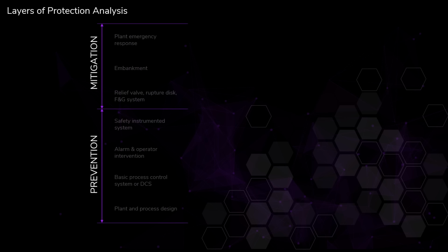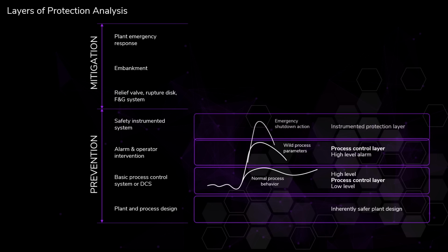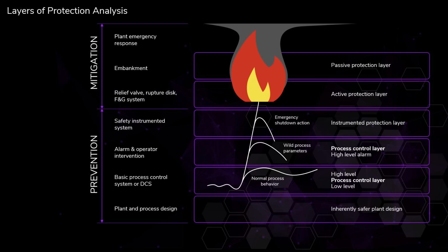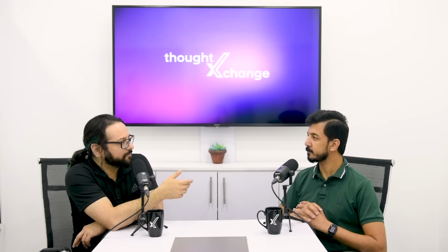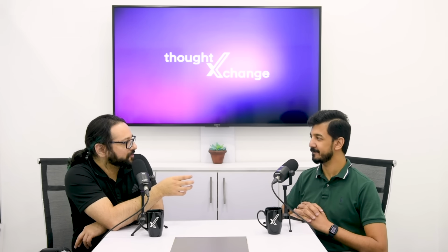That is again governed by IEC 61508. That is layer of protection analysis. So what is layer of protection analysis? Once you have identified your hazards, you might want to put some layers of protection around it to make sure that hazard cannot reach the worst outcome. So, for example, if there's a spill, your first layer of protection would be the coating on the tubing to make sure the spill doesn't go outside into the environment.